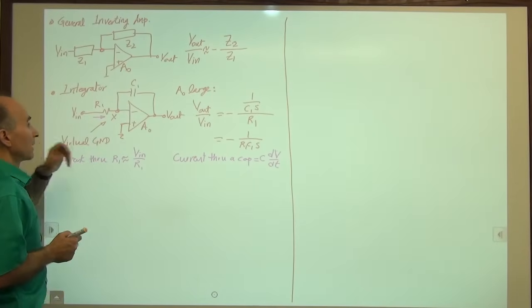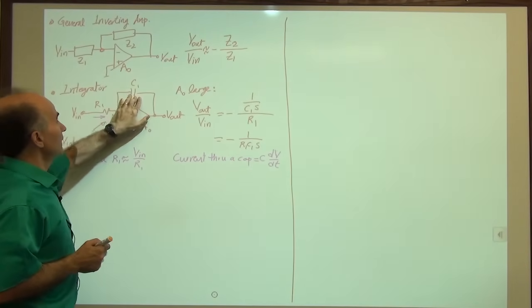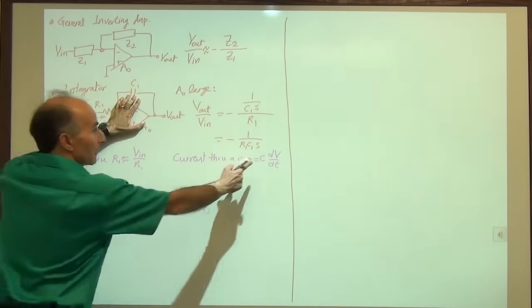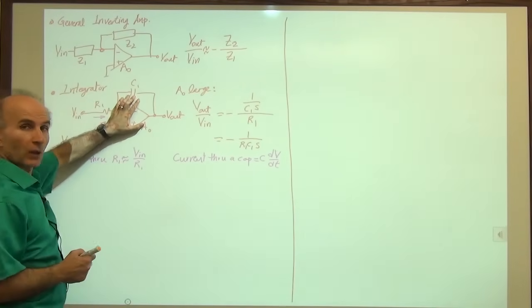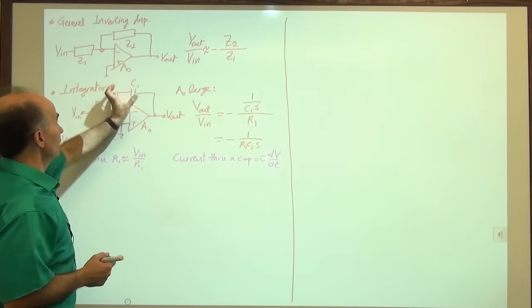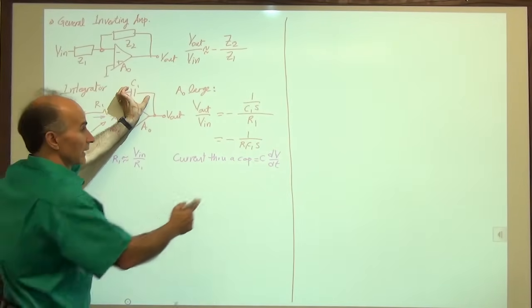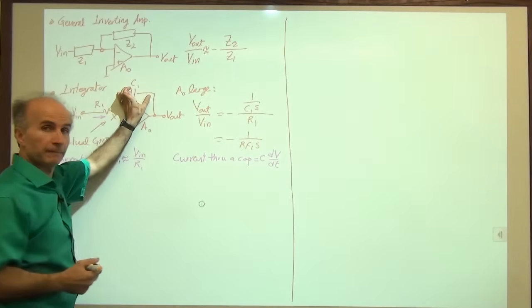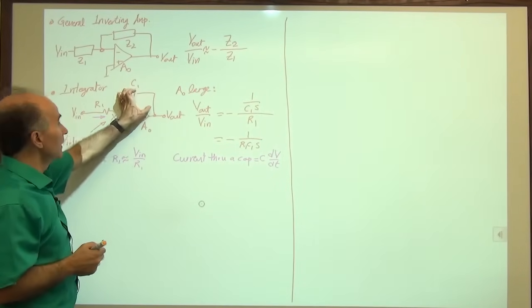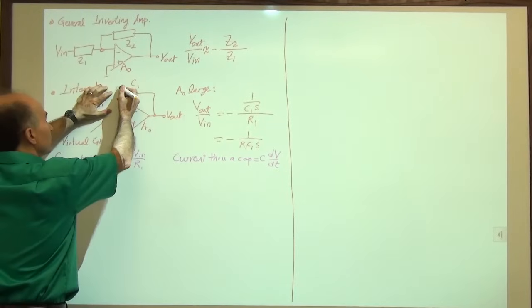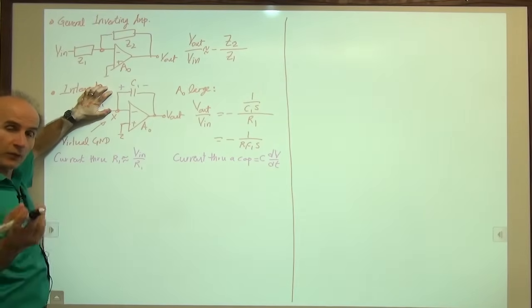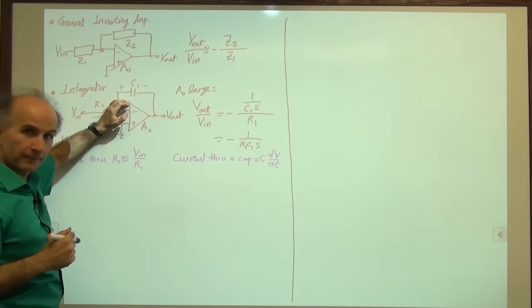All right. Now, can I write an equation for the current through the capacitor independently using this equation? Well, I can say that the derivative of the voltage on the capacitor, times the value of the capacitor, gives me the current. So let's try to do that. Let's assume that the voltage of the capacitor has positive on this side, negative on this side. It's up to you, but you can pick it like this.